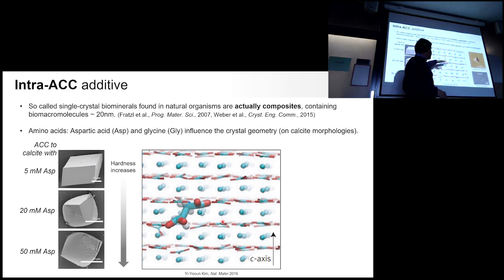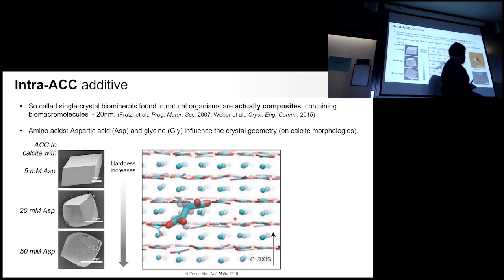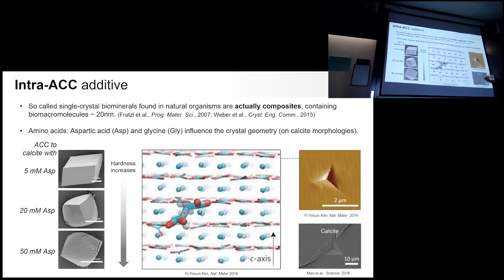And when you constrain the lattice and apply an external force, you cannot deform these lattice planes easily, because there are things sitting between the lattice which restrict further deformation of the lattice. Which is why what you observe is that with this calcite, you see there is a dent, but the height of the dent is much smaller than here. And this is a single crystal. This is a rhombohedra.